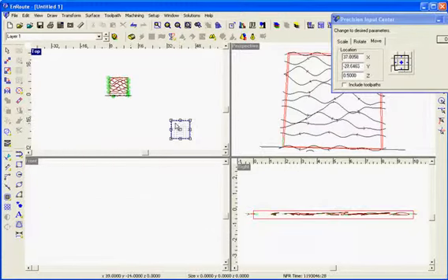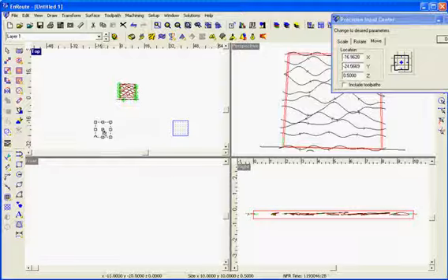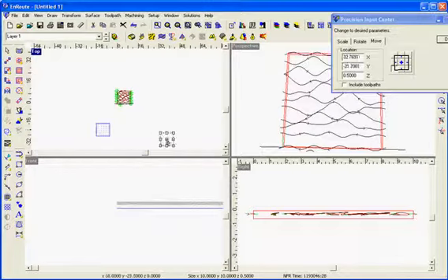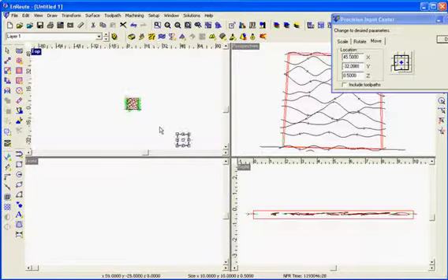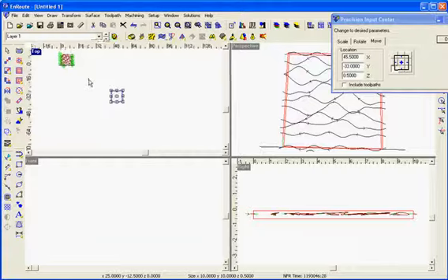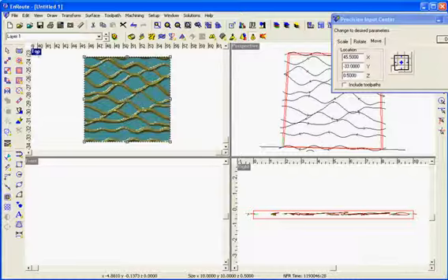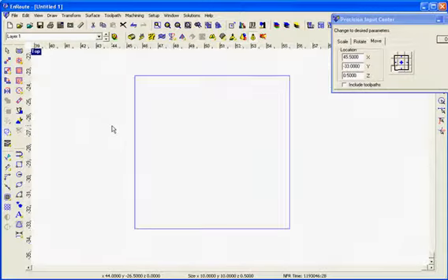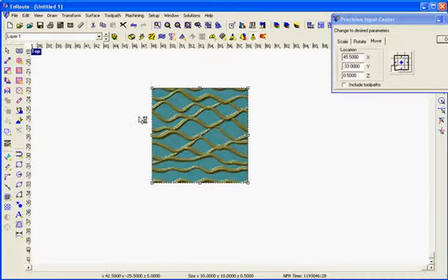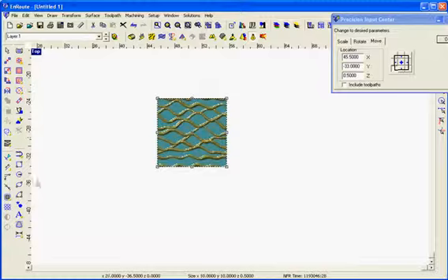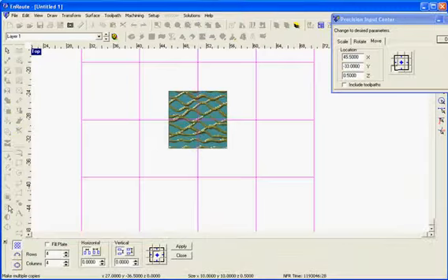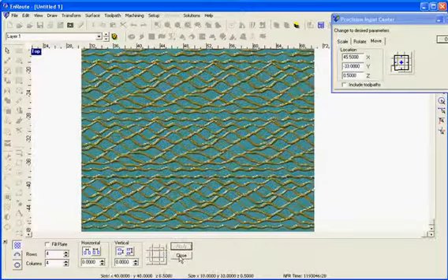During this process, it's likely that because of the merging process, we might be a little bit off from a simulation standpoint with some of these parts, but for the most part, we should see that everything matches up correctly. An easy way to do this, first we'll come in here and zoom in on this a little bit again. An easy way to do this is to utilize the Multicopy tool. So I'm just going to scroll back here a little bit, come here to Multicopy, and in this case I have 4 rows and 4 columns with no spacing. I'll hit the Apply key and then Close.